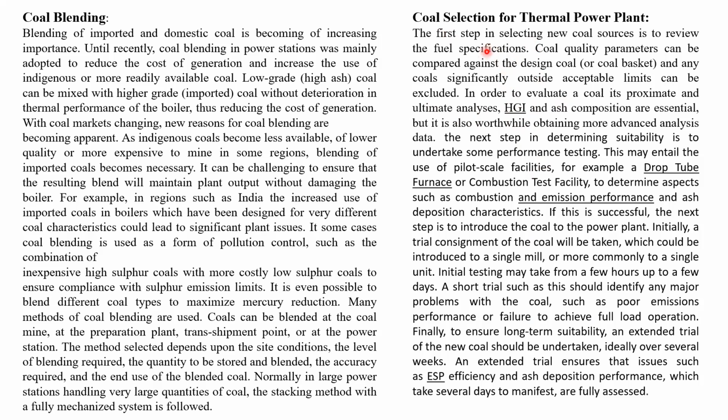the coal. We already know proximate analysis and ultimate analysis. Then one more is the Hardgrove Grindability Index, HGI. The higher the HGI, the softer the coal; the lower the HGI, the harder the coal. These tests we carry out at site or in the labs.